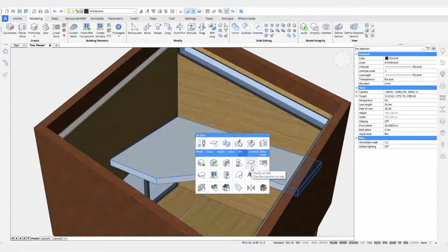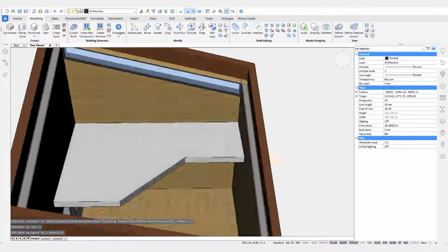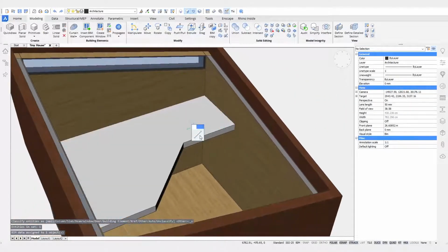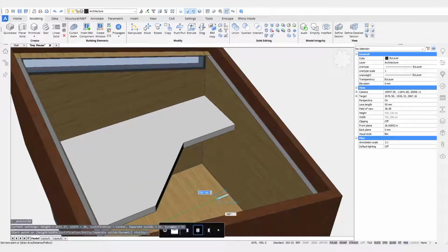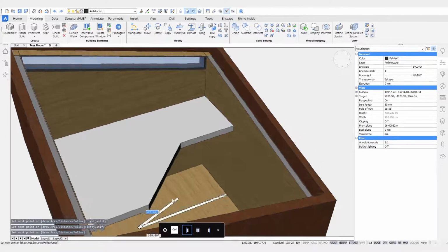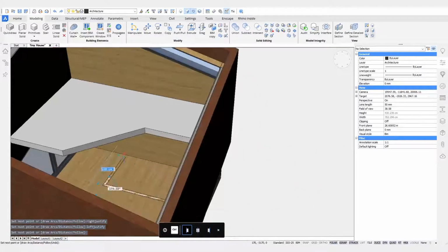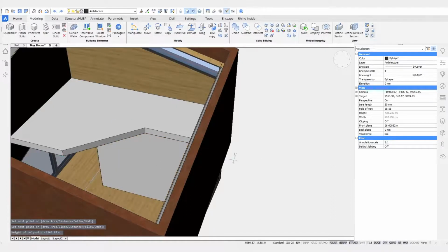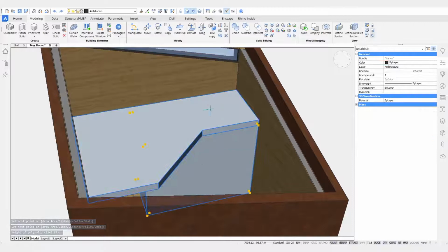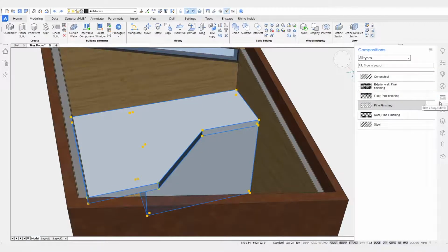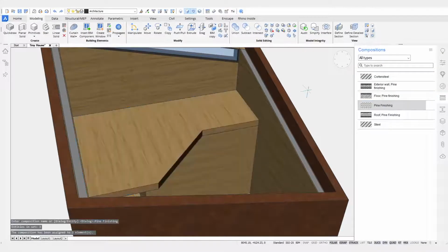I'll just do it. And also, I want to create a bathroom because every building needs a bathroom, of course. I'm going to do that using the polysolid tool. This is a tool to easily create walls, but actually they're not walls yet. They're still just simple solids, which can later be classified manually or automatically by, for instance, BIMFi. And also apply composition here. So again, just the same wood material.